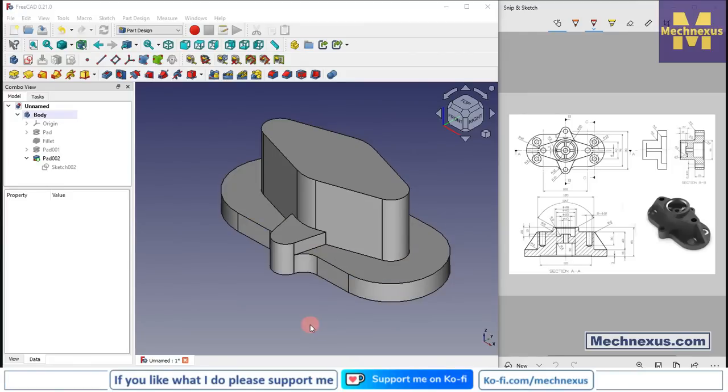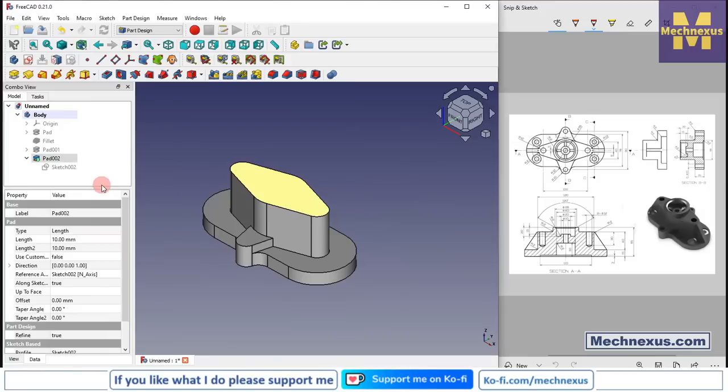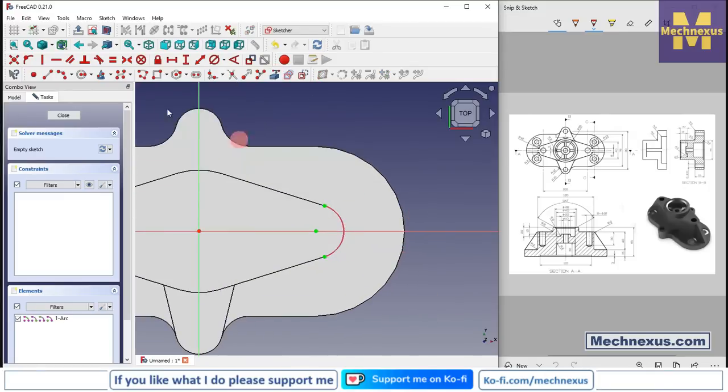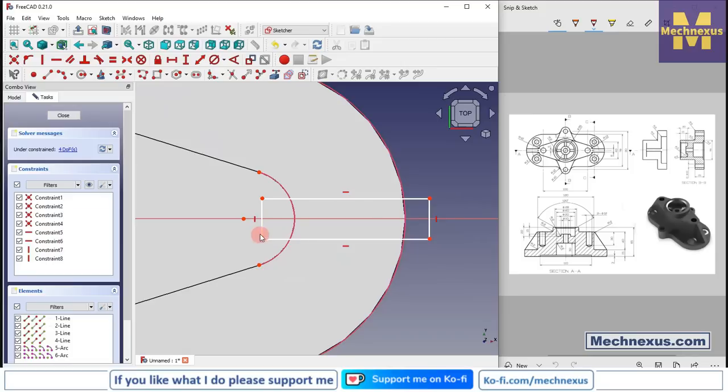but first let's create this rib. So we will select this face and click on the sketch, click on the project geometry and project it, and in the same way also project this edge, and here we will create a rectangle, and here we will provide the symmetry.